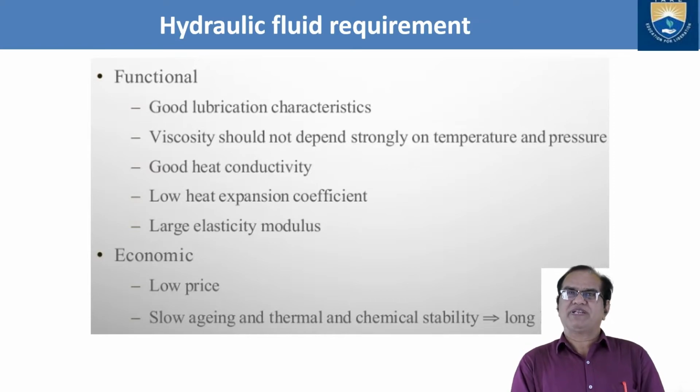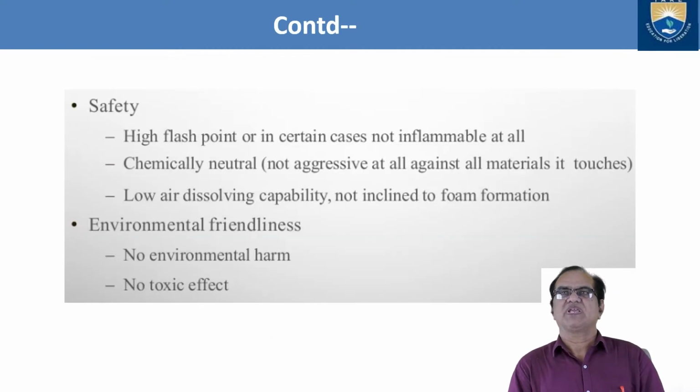Now, hydraulic fluid requirements. We have the functional requirements. Your hydraulic fluid should have good lubrication characteristics. Viscosity should not depend strongly on the temperature and the pressure. Good heat conductivity, low heat expansion coefficient, large elasticity modulus. Economic, it is low priced, low aging, thermal and chemical stability. Safety, it has a high flash point or in certain cases is not inflammable at all. Chemically neutral, not aggressive at all against any materials it touches.